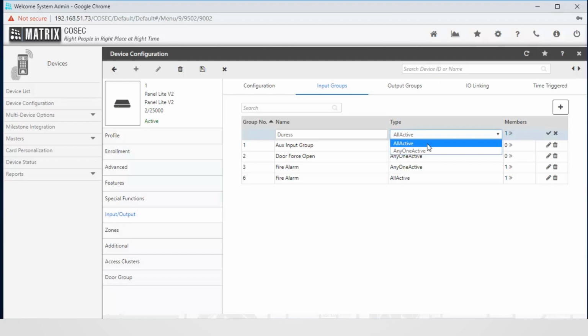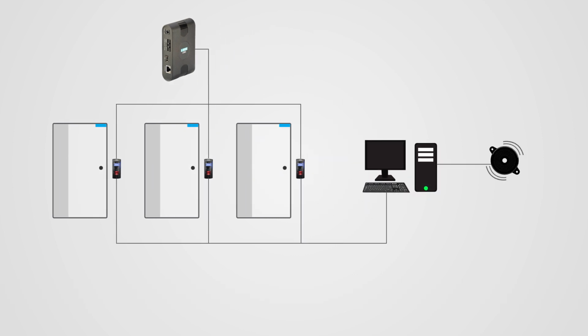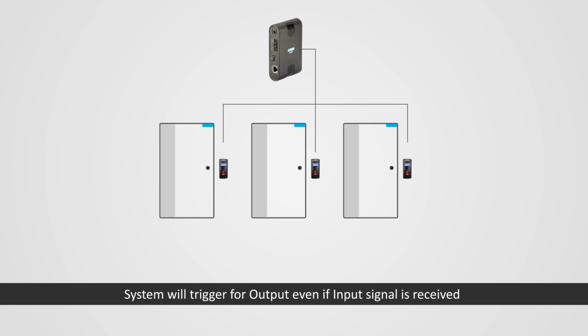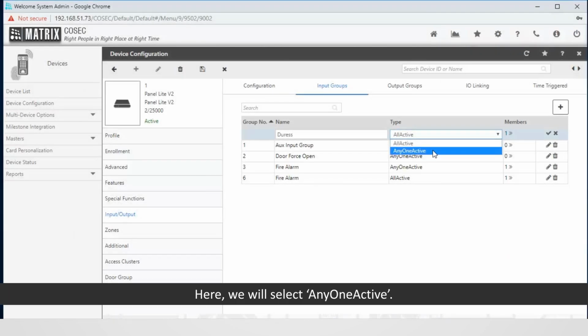All Active: the system will trigger the output only if an input signal is received from all the connected panel doors. Anyone Active: the system will trigger the output even if an input signal is received from at least one panel door. Here, we will select Anyone Active.